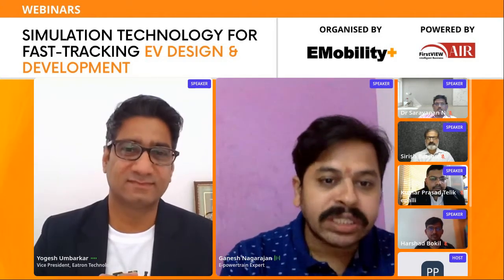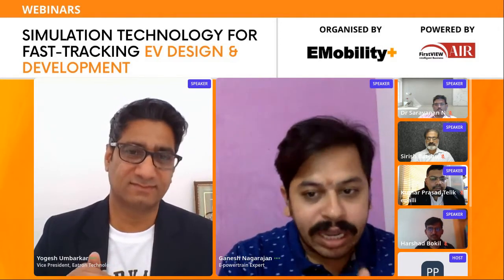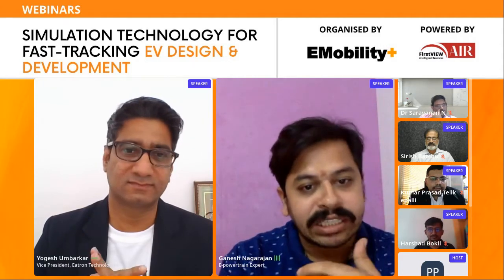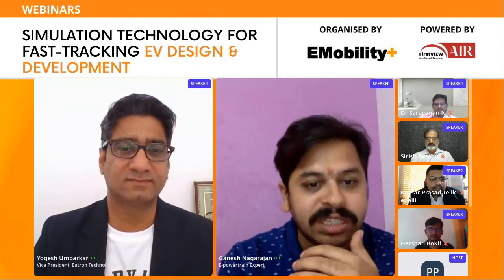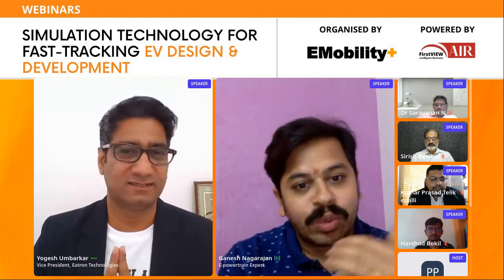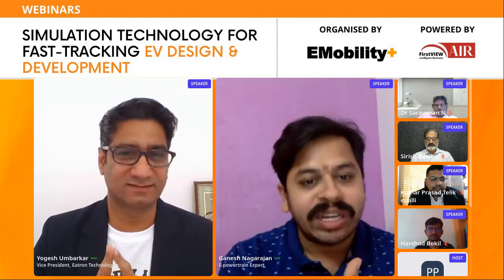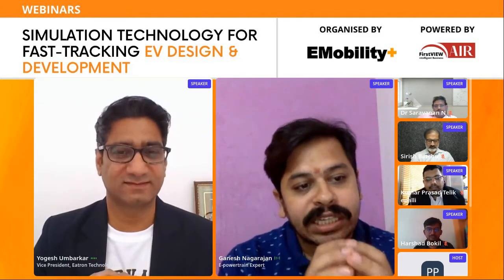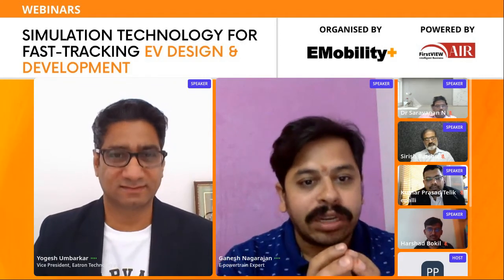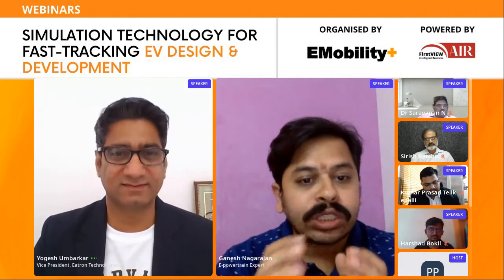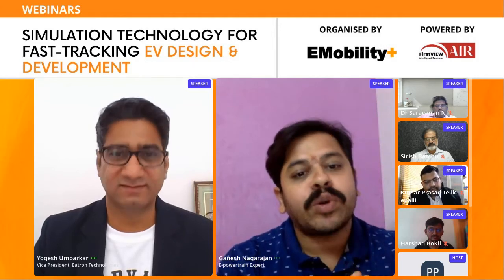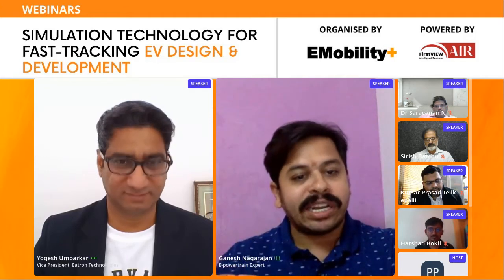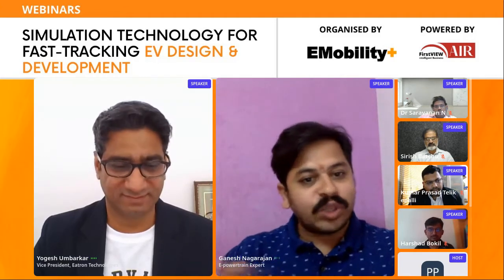By using simulation software, we can predict those things, like Kumar and other people said, the magnet degradation. We can easily predict it by simulation. In real time, how much current on the d axis is going to degrade my magnet, I can predict only in simulations. Also, I can see when it is going to fail, at what life cycle. I can do that only by simulation instead of going through the real cycle, because if I want to build a motor, keep it in the rig, and test it for about 1 lakh cycles, that is going to be quite a long period.